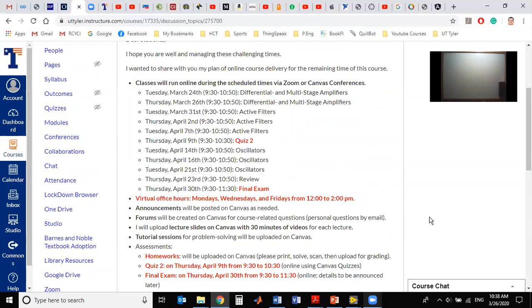And I fixed the reverse connection of the outputs and input ports for the SAR and for the D-latch. So I think now it should work fine. You just connect them, and you have X0 or S0 as the least significant bit, and S3 or D3 or X3 as the most significant bit. So you just make sure that you connect them accordingly. And I also identified R0, R1, R2, R3. So R0 corresponds to the least significant bit, and R3 corresponds to the most significant bit.